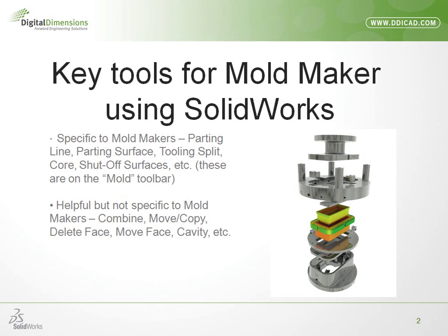as possible. But there are some other commands that you may be used to that are not necessarily specific to mold makers, but are definitely very beneficial. The one that sticks out the most is definitely the combine command. The ability to subtract one body from another, the ability to do Boolean operations, is definitely a big benefit. But there are others. If I'm doing in-context work in a part where I need to move bodies around, move copy is going to be the command I use.